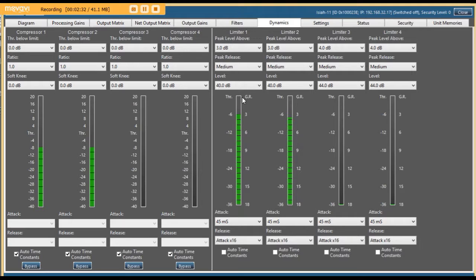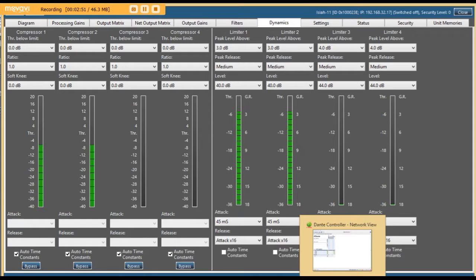be able to handle. And the general bit of advice I often give to people is bass drivers, it's typically 3 dBs, and mid-range drivers it's around 2 dBs. But the best thing to do is consult the manufacturer's datasheet to see what they recommend. So we'll double check that 3 dBs.